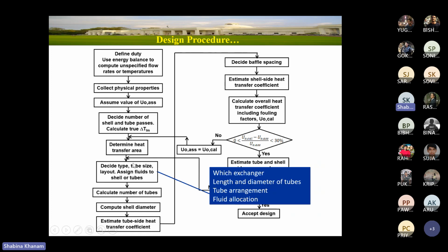And tube size means length and diameter of the tube, or how to see that also we have discussed. I will provide the standard chart, standard table for that. Tube arrangement, that should be triangular pitch, square pitch, whatever. Start with triangular pitch, that is in most of the cases that will work. Okay, so start with the triangular pitch. Please consider these points while designing.